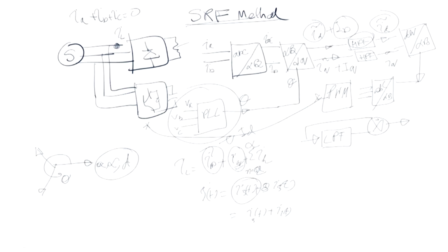So, what happened here? How accurate you set this matters, because it is a DC value. You can set the cutoff frequency of 0.1 hertz, 1 hertz, 10 hertz, and so on. The lower the cutoff frequency you set, the more accurate will be the value of the delta, but there will be a delay in calculation because this low pass filter requires time for settling, and ultimately we need to optimize. So, we can train this optimization and use this ANN. That is one of the works of the ANN I am going to present.